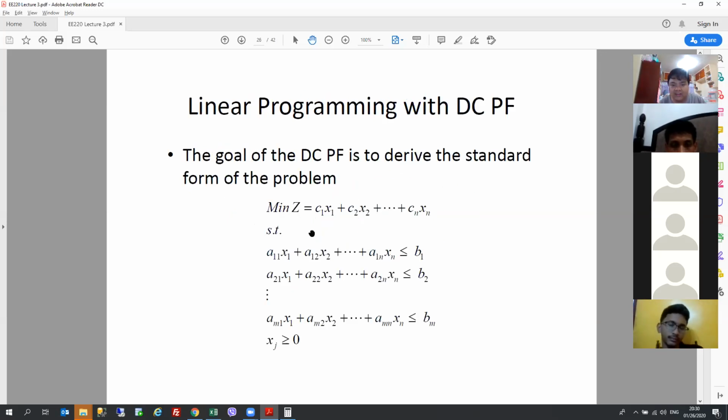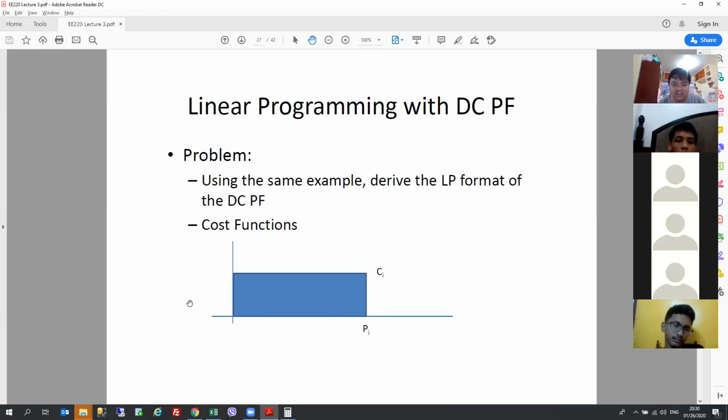And then, going back to the minimization natin, cost function, minimize Z, your cost function, subject to these load flow constraints. Ililinearize na natin yung quadratic function ng generator. So, imbis na katulad kanina na mayroong 4 plus 4P1 plus 0.01 P1 squared, magiging isa na lang coefficient.